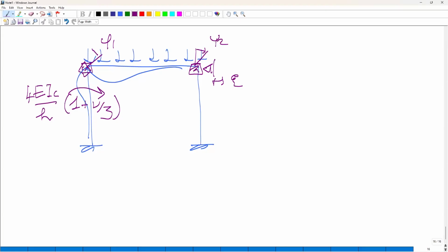Well, you have two ways to go through. In this case, it's quite simple. I expect that the beam will load the columns in the same way, so the axial load in the column will be PL divided by 2. That can be done. So either you estimate axial loads when you can do so by equilibrium, or you simply do one thing. You perform your first step of the analysis without considering the correction functions. So you get a set of axial loads, and then you start iterating your process.